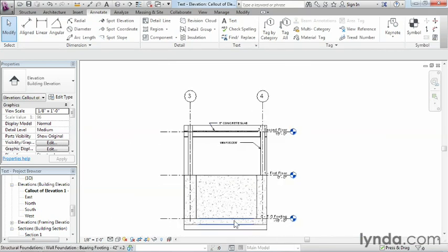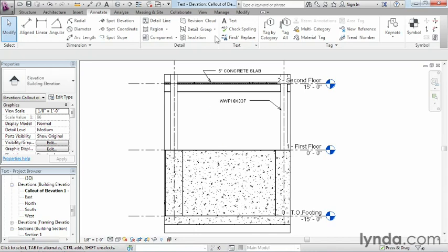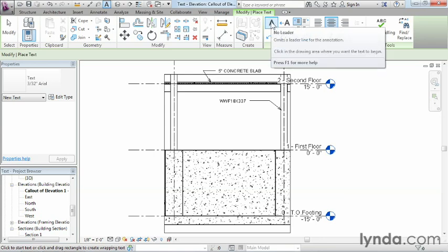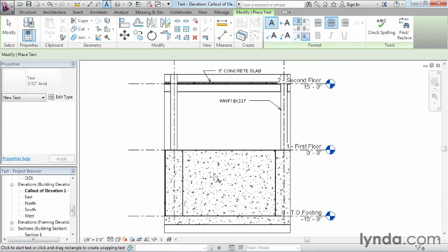One more piece of text we want to do, and it's going to be down here in the box. We're going to come back up here to text, select on text. We're going to do this concrete wall, and it's going to be called beyond. So say concrete wall and then the word beyond. Now I'm going to once again just do that box, if you will, kind of leader. So we're going to come in here with the text without the leader associated with it.